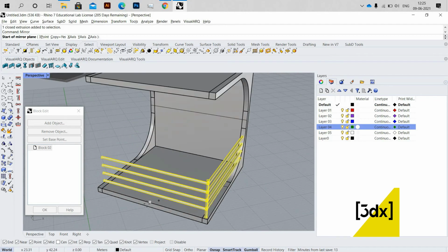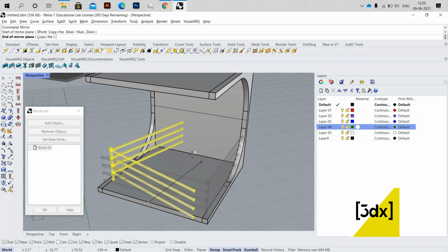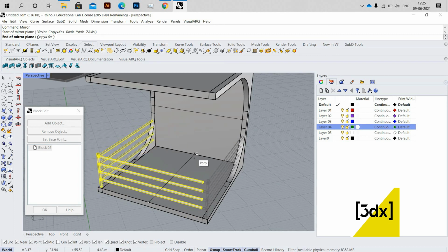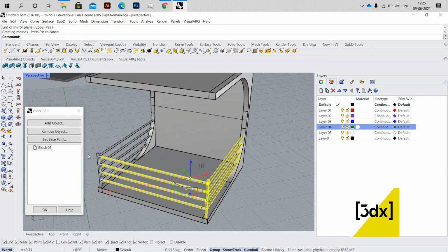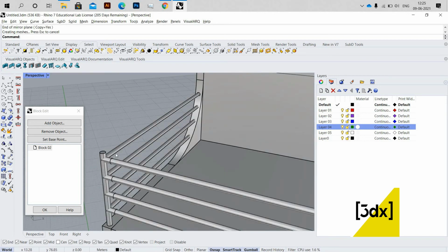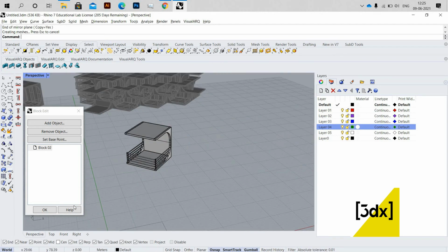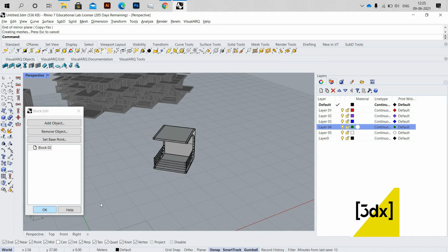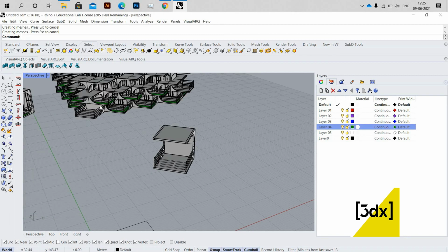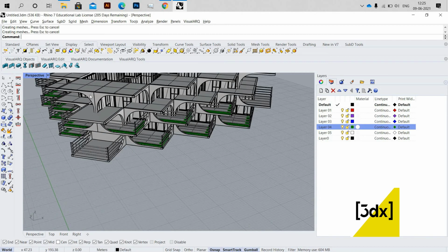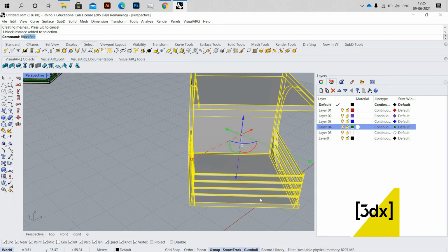If you don't get this middle intersection, you can see at the bottom there are certain lists. In that, press snap, and you will get all the intersections, like you will get all the elements like this. So you have to press OK. So this is what I need.